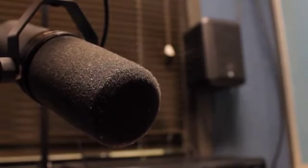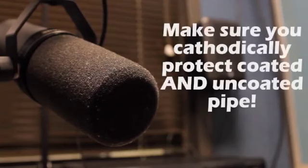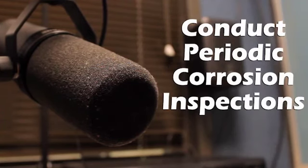There are ways to prevent corrosion. If your pipe is coated, great, you're one step ahead. Even if it isn't coated, make sure you cathodically protect it. You can also paint above-ground piping and components to protect against atmospheric corrosion and conduct periodic corrosion inspections, including measuring pipe-to-soil voltage for buried steel lines.